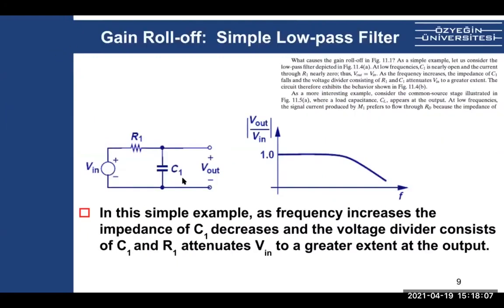All right. So now this is the term called low pass filter, high pass filter. Logically, when I tell you, draw a low pass filter, without a blink you should be able to draw this, right? Why? Because at low pass, what is this cap at low frequencies? Open, right? Because it is 1 over j omega C. So if it is low frequency, just take DC as an example. This is 1 over 0, so it's infinite impedance, which is open. Whatever input shows at the output, right? There is no leak anywhere. So that's why V out over V in is 1.